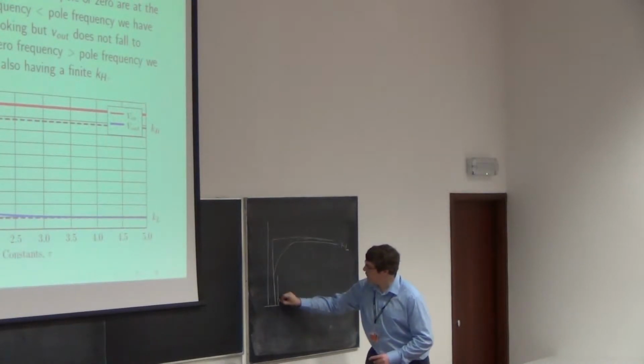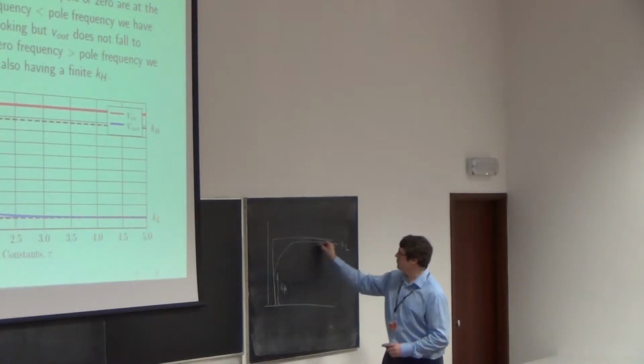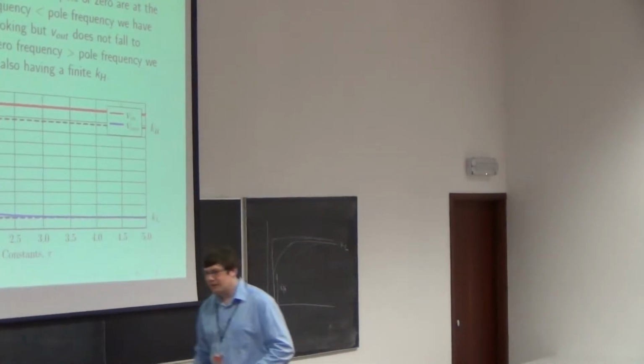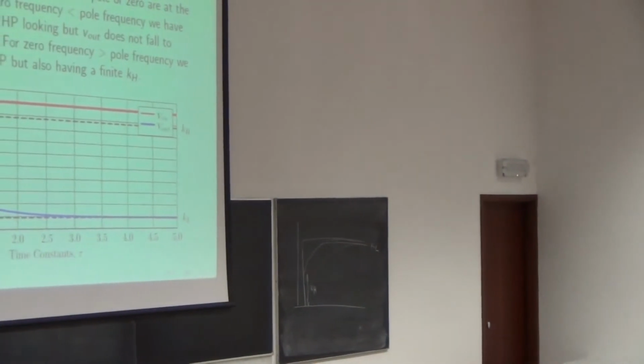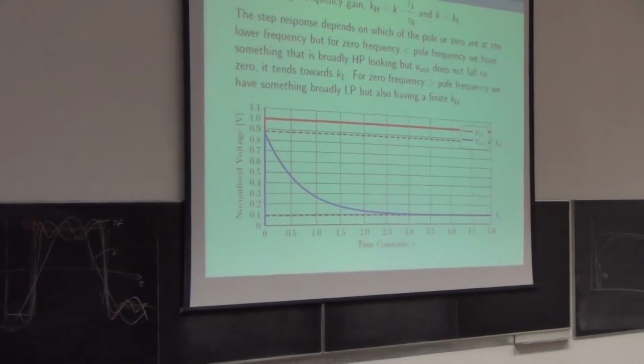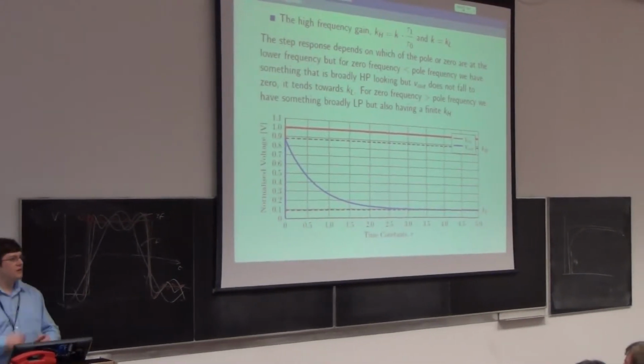And this distance here will be proportional to my KH, which is different from the standard low pass, which maybe just looks like that. So you get this step. Nobody got the biscuit. Never mind. If you want to try it in Spice, put up some simple passive pole zero circuit and you can observe the height of it.